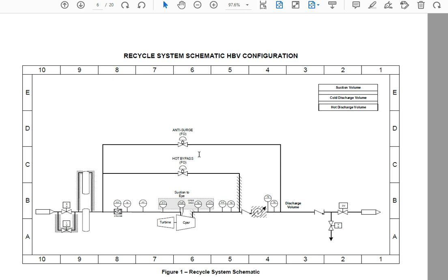And by the way, how am I calculating pressure drop across this piping? That is a tricky problem. Really, I ought to be doing CFD. But if I keep the velocities low, I can get away with using just standard pipe flow equations using assumed roughness and just textbook pipe pressure drop formulas.